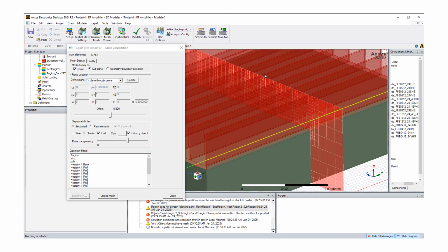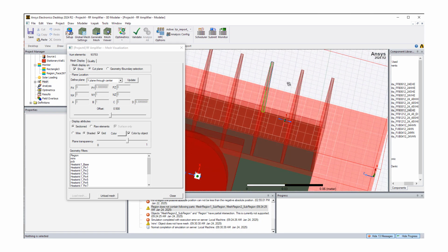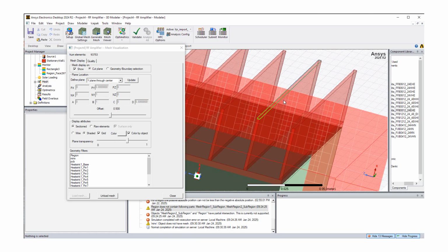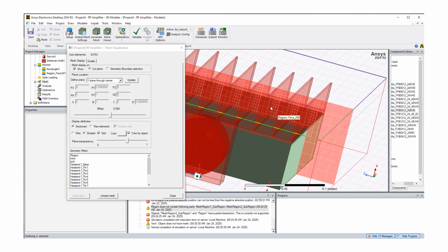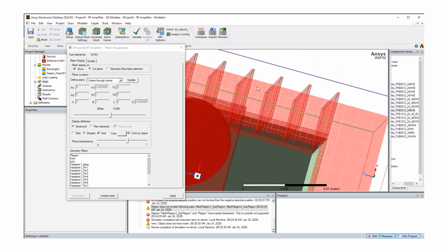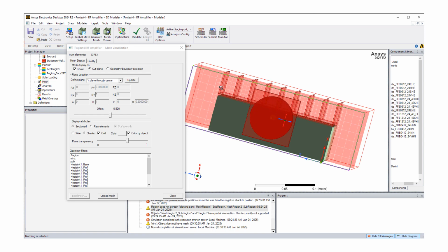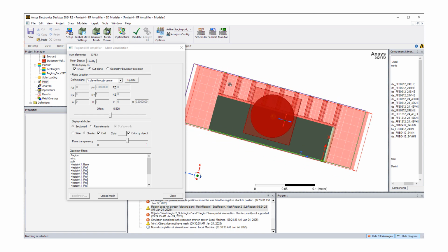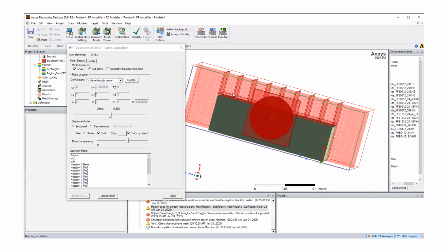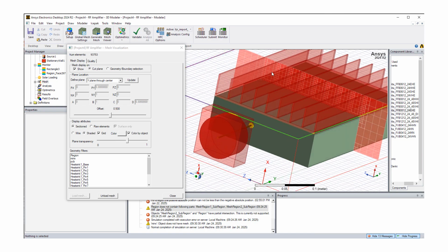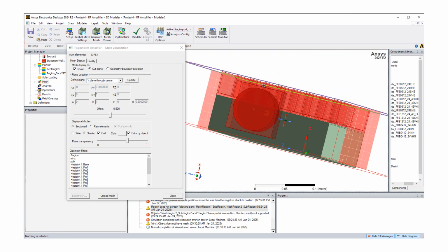amplifier and the heatsink. And here you can see how the meshing is done. As you can see, it's decent, but a fairly coarse mesh. You probably want to do a better job resolving the flow, not just maybe 4 elements in between, but maybe go up to 10, 12 elements in between fins.